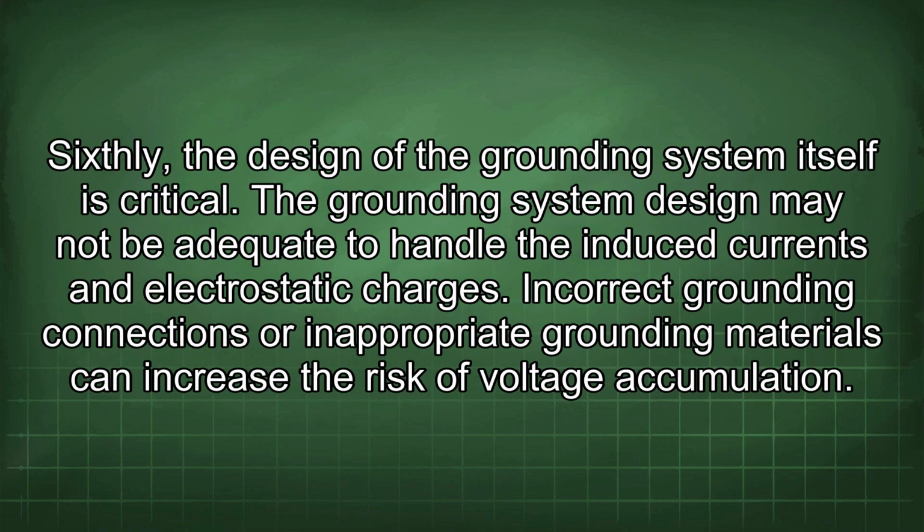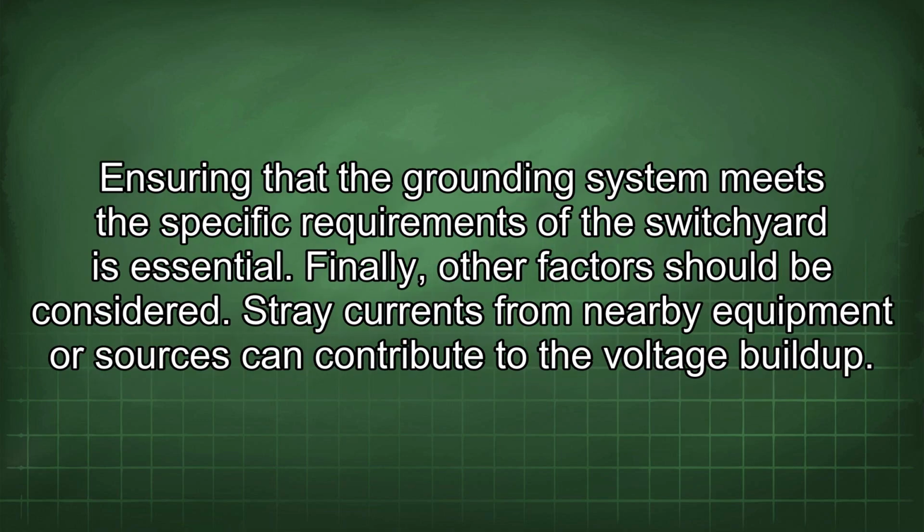Sixthly, the design of the grounding system itself is critical. The grounding system design may not be adequate to handle the induced currents and electrostatic charges. Incorrect grounding connections or inappropriate grounding materials can increase the risk of voltage accumulation. Ensuring that the grounding system meets the specific requirements of the switchyard is essential.